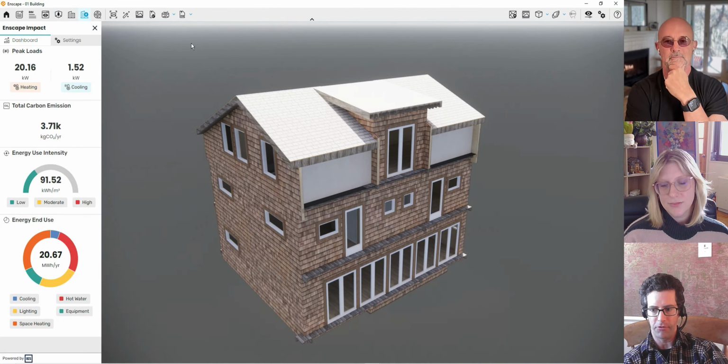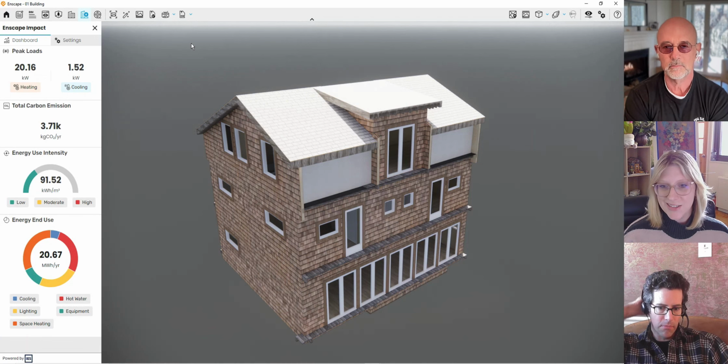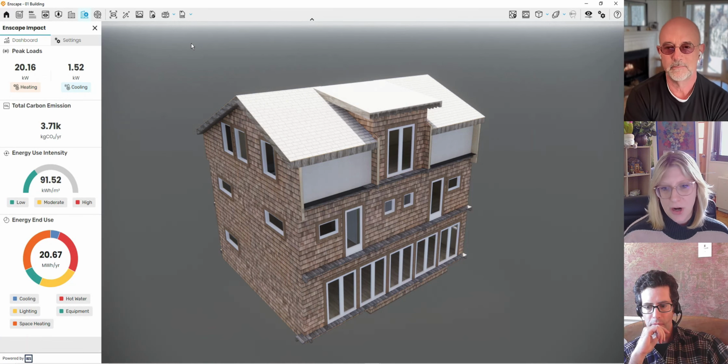Don't try to run it as a multi-building project. Isolate them, and you'll have Impact results for each of the buildings and each of the views as you drive Enscape from those views. It'll give you not only faster calculations, but also much more accurate ones if it's focused on individual buildings as opposed to a whole site.